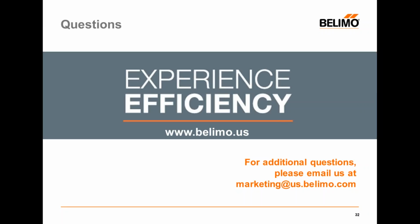Okay. Next question. What is the most common smoke control strategy in a healthcare facility that is considered a high building? And this is in Canada. Considered a high building, is it meaning a high-rise building? If that is the case, generally what I see most commonly is fire smoke dampers interlocked with the starters on large air handlers. So as the duct detectors in the areas being served by the air handler sense smoke, they break the contactor that controls the fan or the contactor on the VFD controlling the fan, and that in turn shuts all the fire smoke dampers closed in that application.